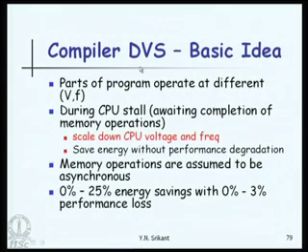So, memory operations are assumed to be asynchronous. So, they go on independently of the CPU and they always operate at the highest voltage and frequency. It is the CPU whose voltage and frequency will be changed. Schemes of this kind have been shown to provide 0 to 25% energy saving with 0 to 3% performance loss.